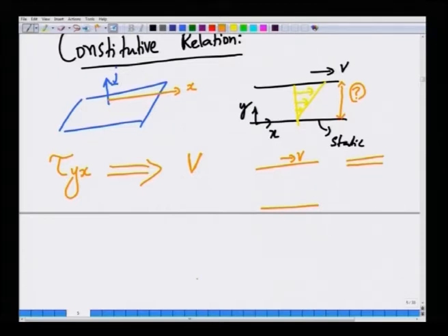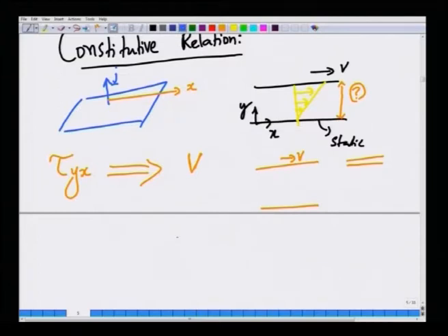Okay. Also, from a physical point of view, if the entire fluid moves with a constant velocity, then there cannot be any internal viscous stresses generated, because that is merely rigid body motion. Okay. Stresses are generated in a fluid only if there is relative deformation between 2 points. Okay. 2 points move past each other relative to each other.